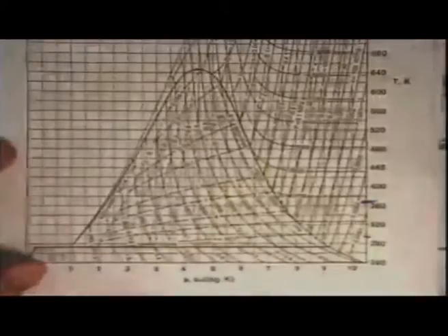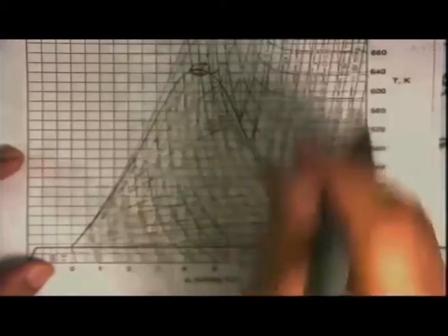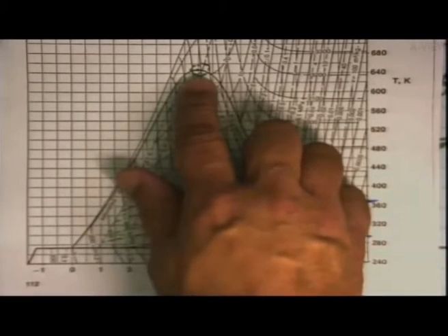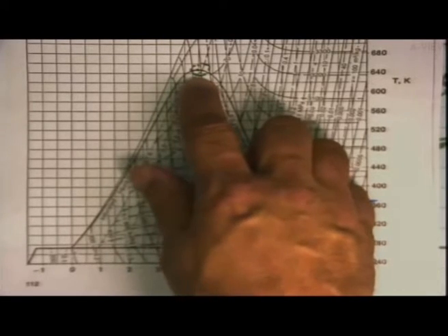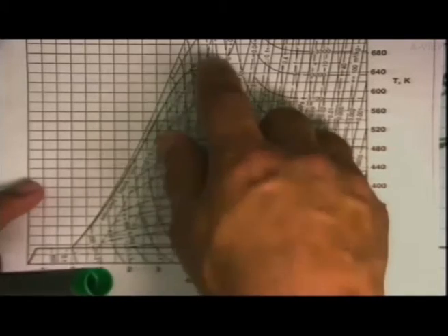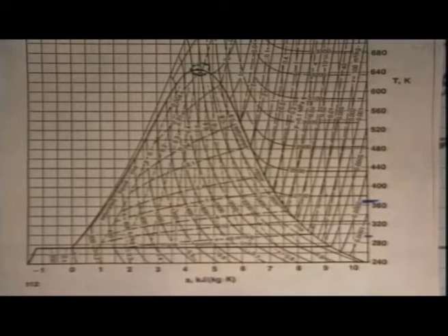I should also mention though that equations of state and the plots that we have are pretty good in most places, but right near the critical point, we have a singularity in the mathematics, and it's very difficult to do the programming. And so now gradually people are saying that, okay, let's not get too tied up by forcing the critical state conditions to be there, but it's okay that in this region, the substance is a homogeneous thing and we do not see any phase change above that pressure. Okay, so that's something more about the critical point.